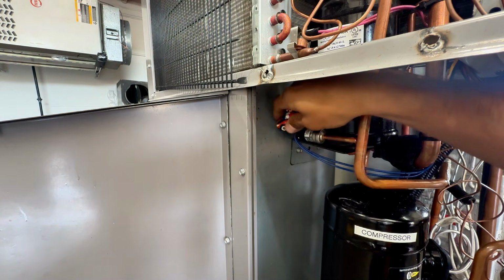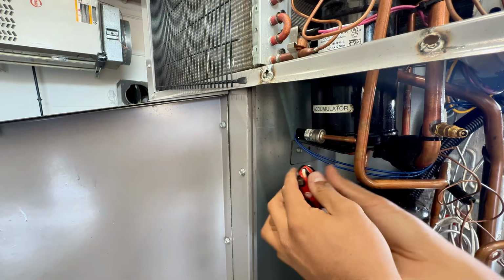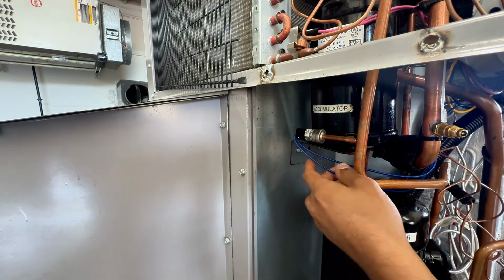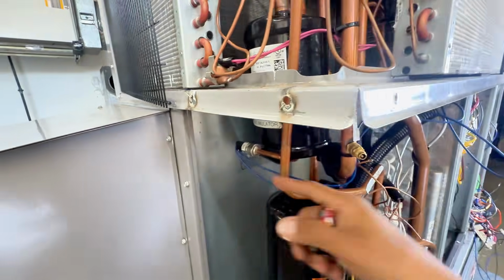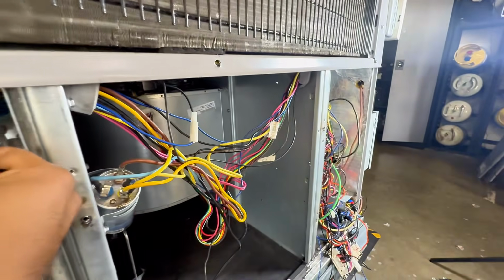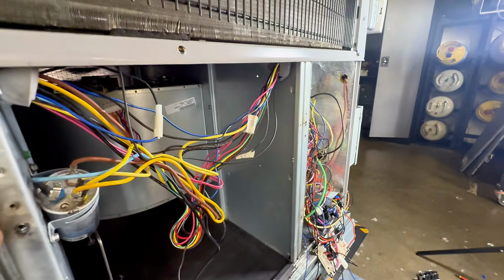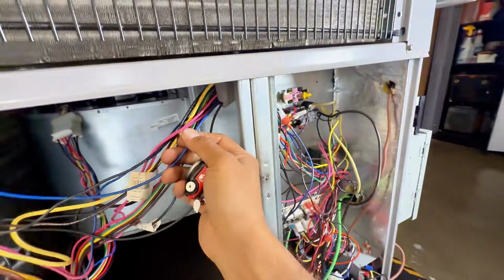So if there's an issue with the pressure, then, of course, that's going to open up. Mario's going to be stuck over here. You've got to fix the refrigerant issue so that the 24 volts can go through. But let's say it's good. And it comes out from one wire in, one wire out. If I pull this wire right there, it is this one here. This blue one right there.